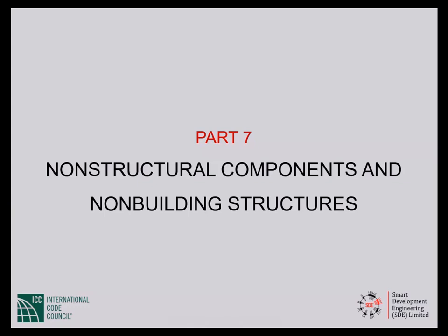The word spectral, very briefly: the spectral displacement is the same as the maximum displacement of a structure, specifically a single degree of freedom system, which means only one component of motion of one mass is possible.